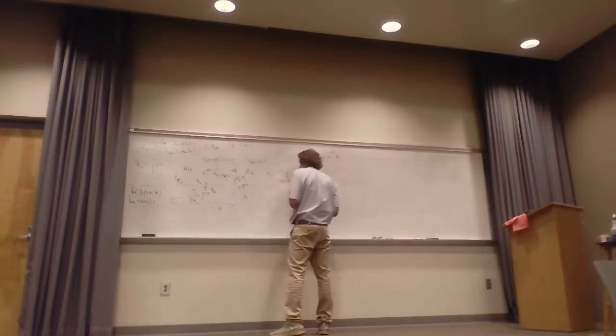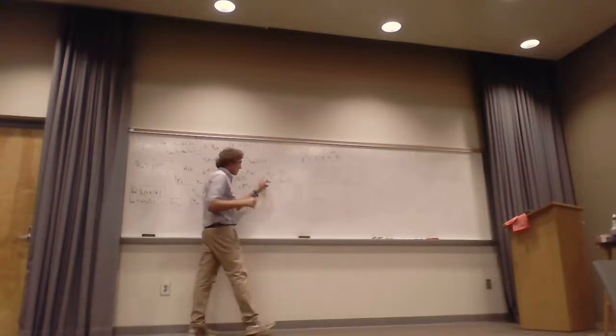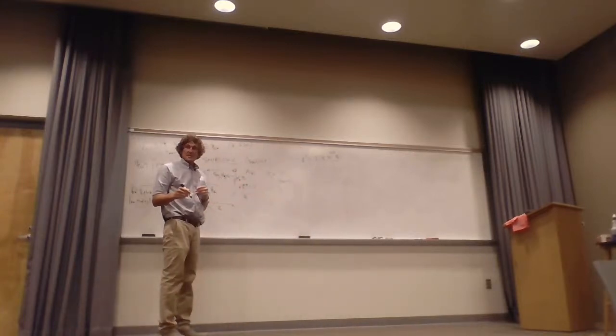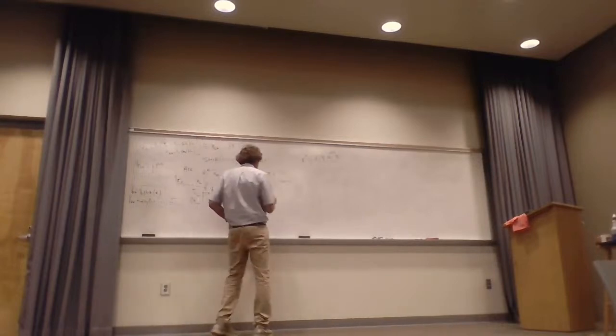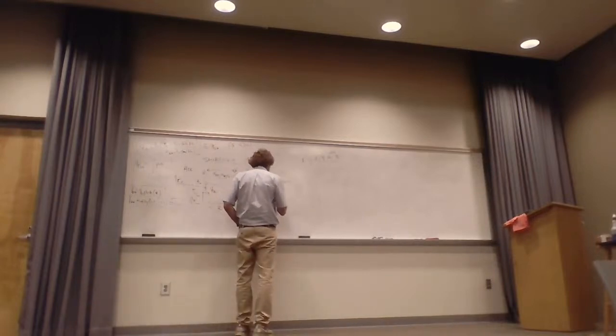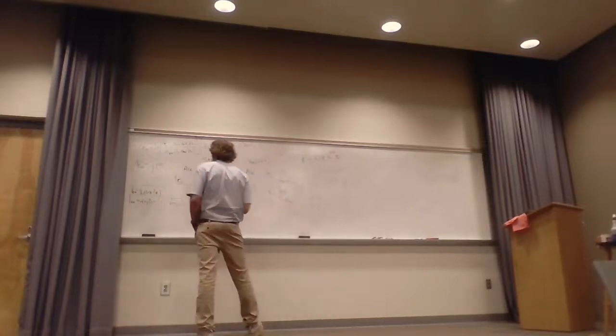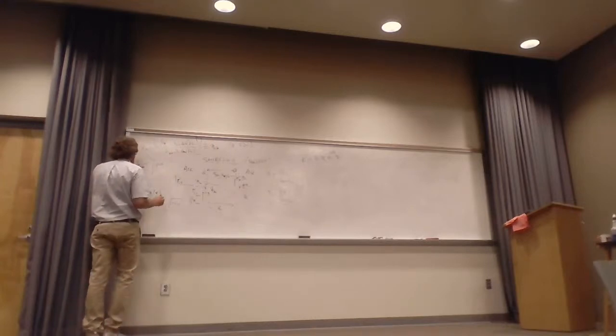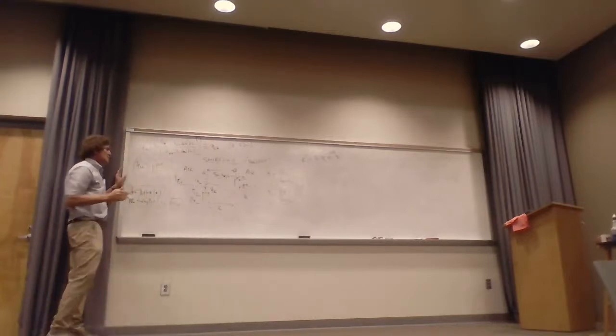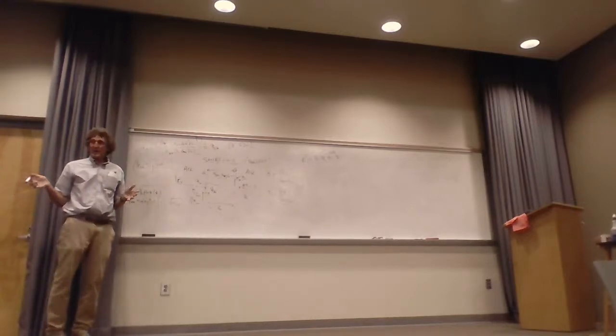Here's something neat. The first one is this. The second one is twice the impedance you're going into, eta naught, over eta naught plus eta shield. Now here's something interesting. This value of eta shield is super small compared to eta naught.